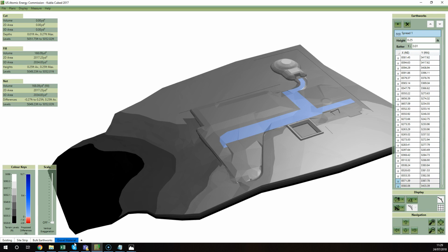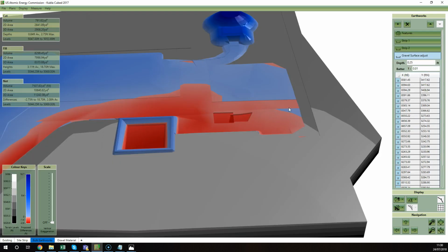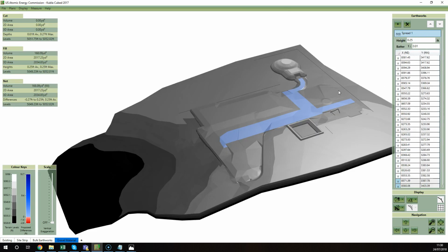So you can keep creating more phases for different materials. That way you can have your cut and fill of your bulk earthworks with the strips adjusting to the subgrade, and then fill in those materials using spread elements. In the report, you should have those categorized if you name them. So it's quite complicated, and it's worth playing around with the different methods.